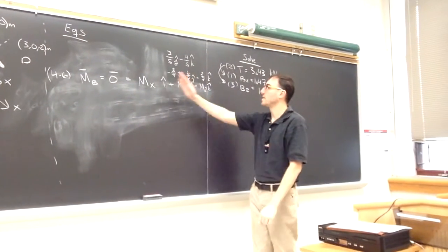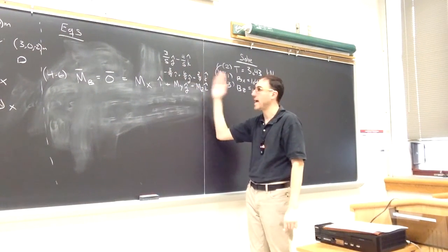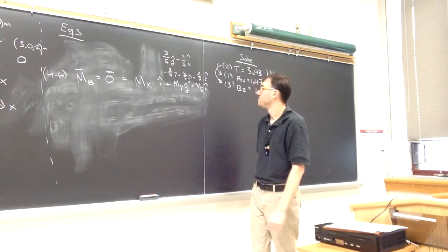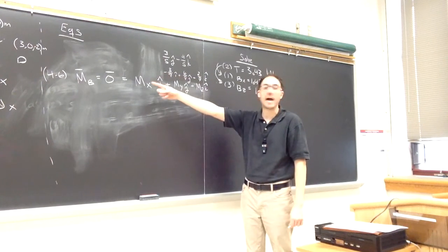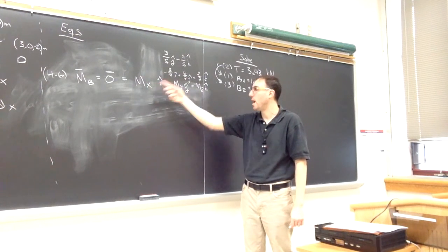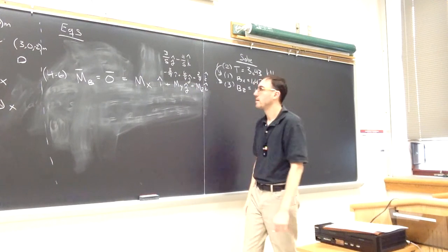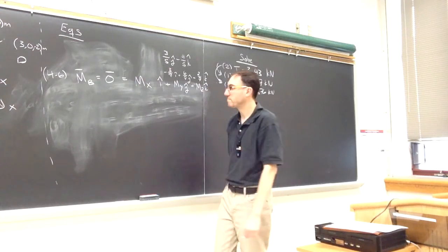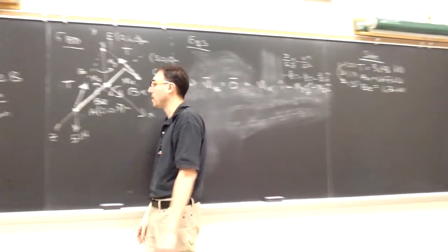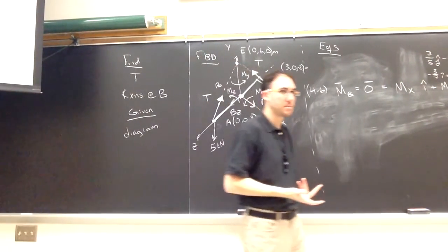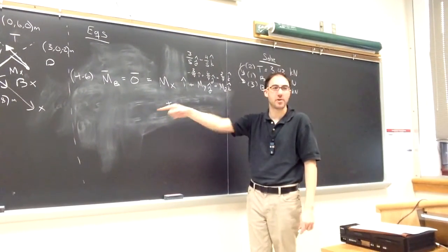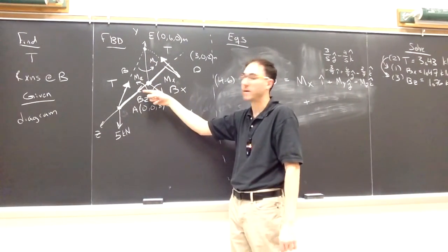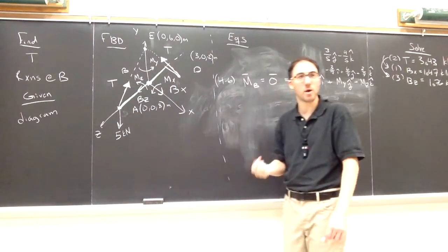It's very important not to forget the I hat or j hat or k hat here, and also don't forget the moments in general. All right, so from the 3 couples, I add that to my right-hand side. One is around I, one around j, one around k. So this is the magnitude of the moment, but also I need its direction. What else causes a moment around point B then, besides the couples? The 2 tensions and actually that 5 kilonewton force as well. So the forces that are not passing through point B, all of them will contribute to the moment around B.